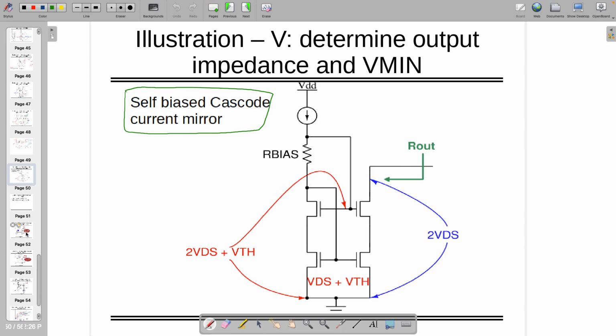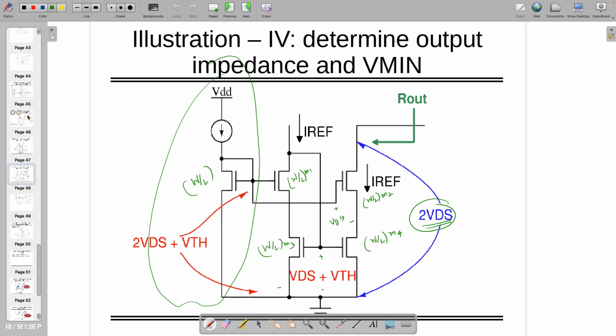It has one branch less than what we had, right? You can see there were 3 branches. If supply voltage is equal to, let's say, 1 volt, if IREF is equal to, let's assume, 10 microampere, and each one of them is also the same IREF, if I'm doing this one, the total current flowing through this circuit is 40 microampere multiplied with the supply voltage of 1 volt. So the power consumption is 40 microwatt, right, in this circuit.